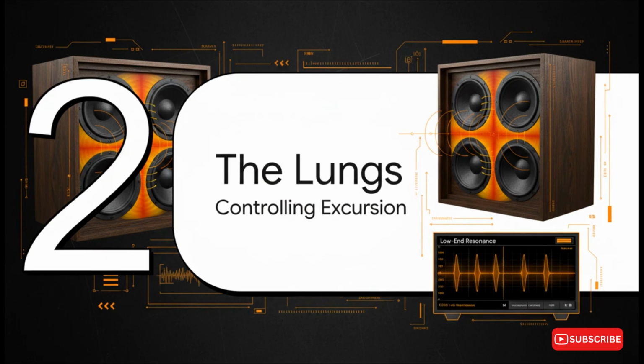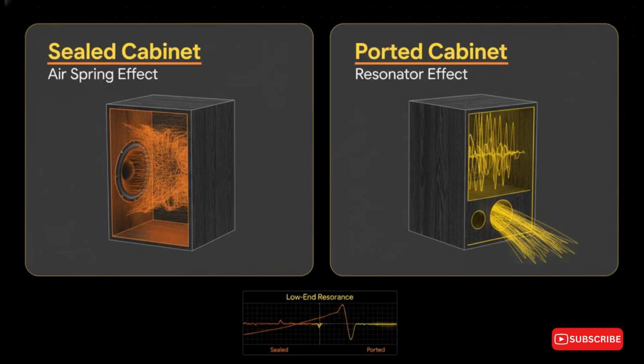Internal volume, controlling excursion, and thump. This perfectly illustrates the physics of air within the enclosure. Broadly speaking, we have two main approaches. A sealed cabinet uses that internal volume of air as a direct compression spring, which creates a highly controlled, tightly regulated environment for the driver. Conversely, a ported cabinet operates as a tuned Helmholtz resonator. It uses a very specific volume of air connected to the outside world through a mathematically tuned port to physically reinforce the bass fundamentals. It effectively creates an acoustic filter that amplifies those lower frequencies.